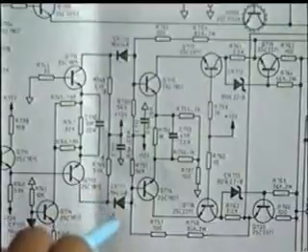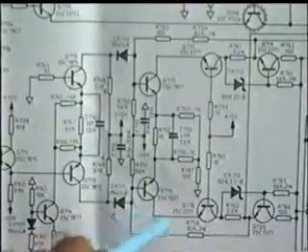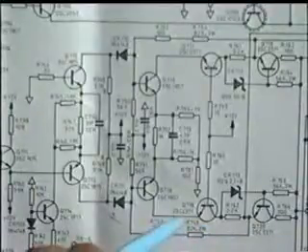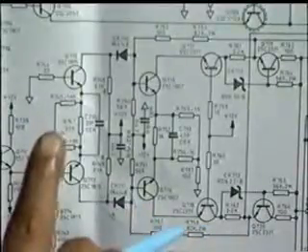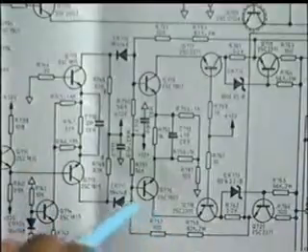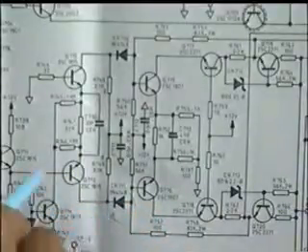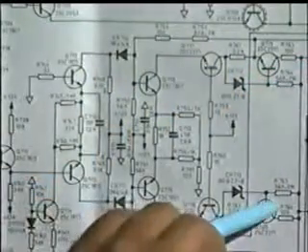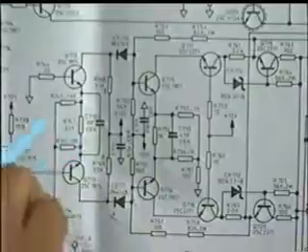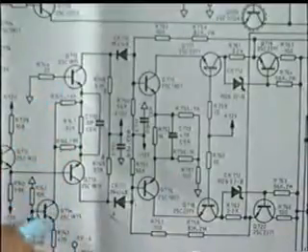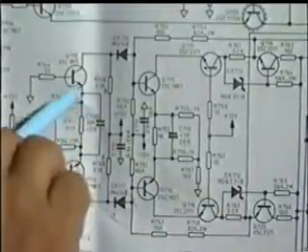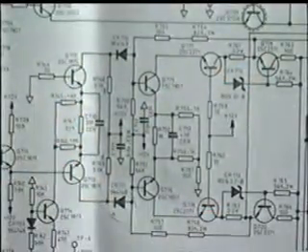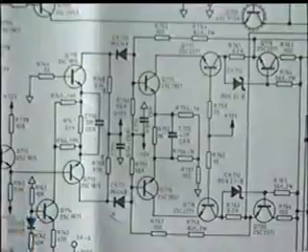Since your signal is amplifying in only one direction, it seems only one plate is working. Therefore, check systematically whether this plate is working or this one. They are bifurcated from this point, so let us start from here and see whether the sawtooth is coming.